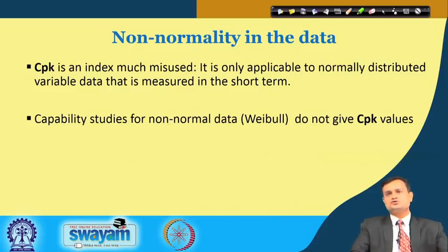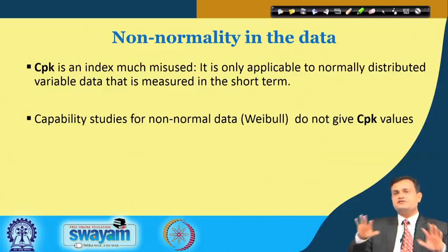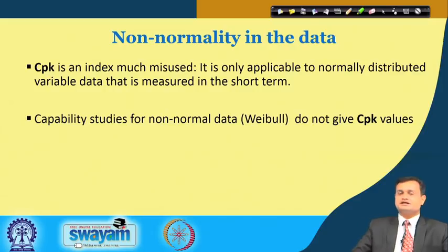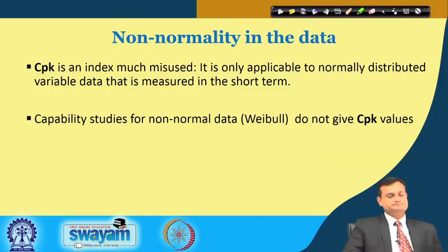Now, you need to take corrective action, short term or long term. As I mentioned, short term you can just shift the mean and try to avoid producing scrap, which will give you cost saving, but this is just a temporary measure. For long term you try to replace the part, set the process, develop the skill of the operator, and see that your process can remain at a particular targeted value over a long operation period.